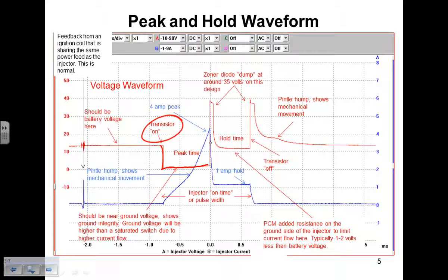So your voltage is going to be much, much lower on low amperage circuits when you're talking about ground voltage. The higher the amperage you go on a circuit, the higher your ground voltage is going to be. Fuel pump grounds, 400, 500 millivolts is not uncommon on a fuel pump ground because you're talking 10 amps of current flow on some of those.